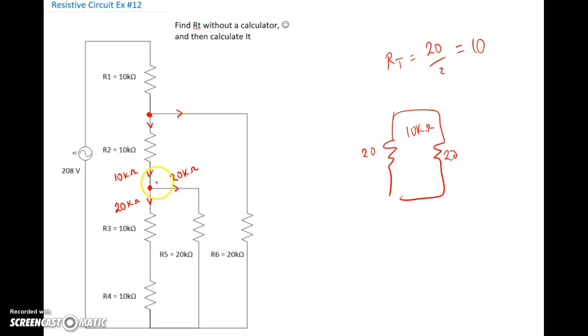And then we're just moving our way up. We're going to go through this other resistor in series. So 10 kiloohms for 3, 4, and 5, plus the 10 kiloohms for R2 gives me 20 kiloohms for all this down here. Let's see what's in this rung over here. We've got another 20 kiloohm resistor. Beauty, we have the math over here. 20 and 20 divided by 2 paths gives us 10 again.